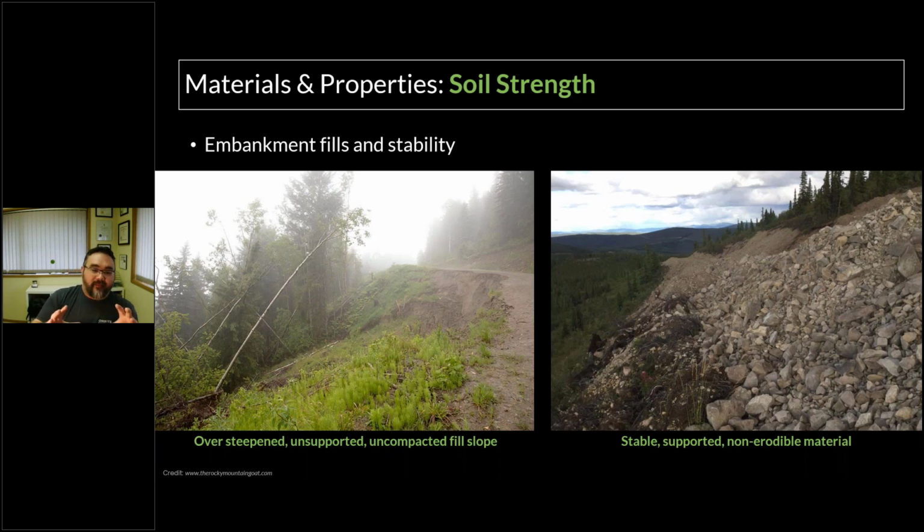So it's not just the overall shape of that, but the permeability or erodibility on the surface, but also understanding where that groundwater level is and how that may also impact your fill slope. So all of these things are a bit broad in the concepts, but how do we fit these into the road design? And that's not my side, that's Matt's.